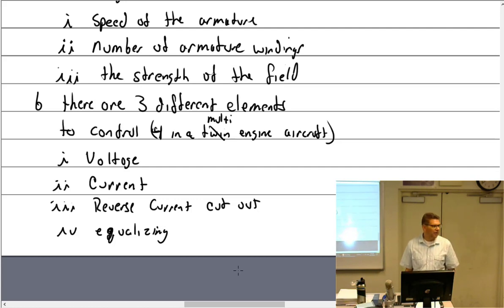In a multi-engine aircraft, you cannot have one generator that is outputting more than the others. Then the others just become more of a load. It doesn't share it, and so one does all the work. So you have to equalize the current. No, you actually have to parallel. You have to actually adjust it.